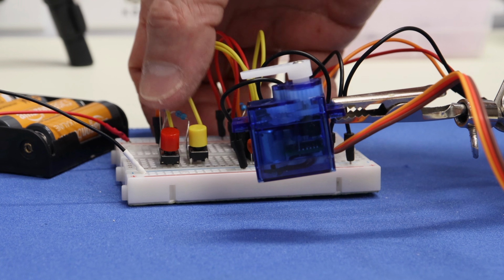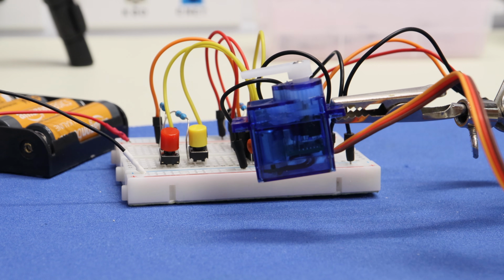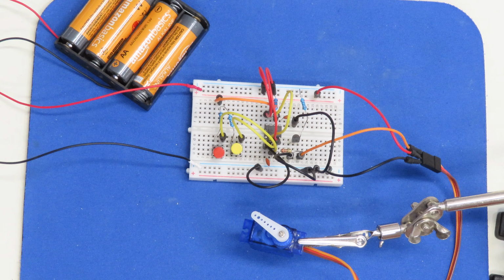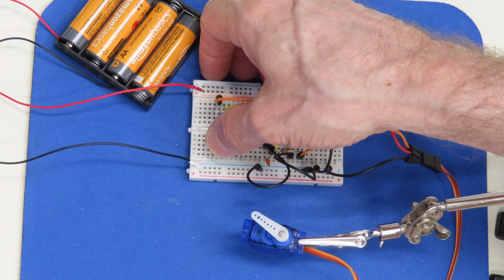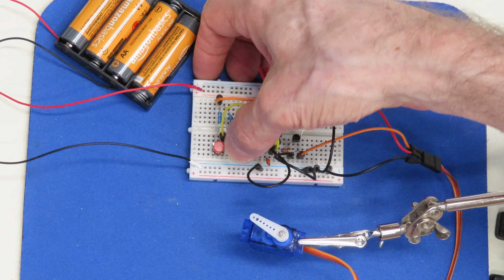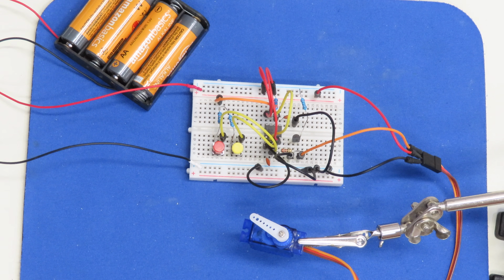One thing I notice, compared to some Arduino circuits, is there's no chattering on the servo when it's sitting there stationary. It's just sitting there perfectly stationary doing nothing, which is actually great. And that's because, of course, it's not actually getting a signal right now. And so it does have an advantage over that kind of a system. And you could use something like this to actually drive a servo motor, not just test a servo motor, but of course you would need to experiment a bit with the value of resistors that were attached to the switch or whatever it was that you were using in order to drive the motor. But again, another great use for a 555 timer.